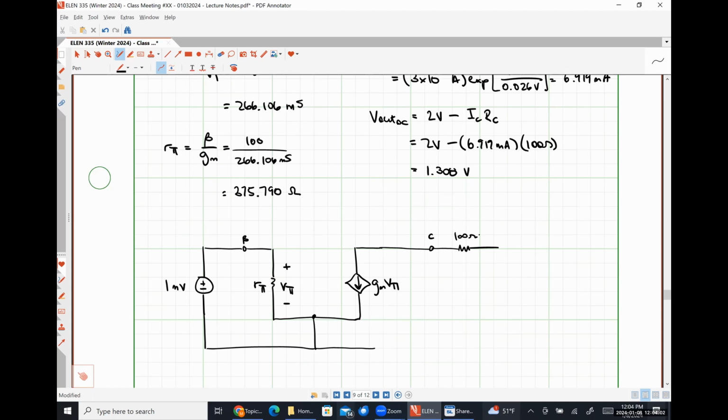So we turned off our large signal VBE already. So that's why there's 1 millivolts and not 0.8 volts plus this, right? So this short circuit down here is effectively us turning off our large signal VBE. And then we're going to short this leg of the resistor to what's called a small signal ground or an AC ground, because that's us turning off our 2-volt supply.